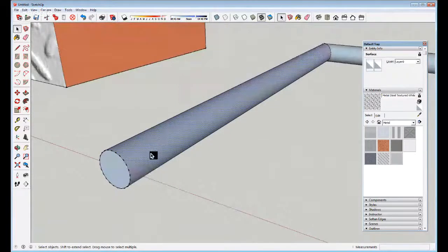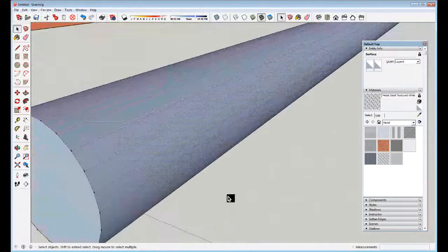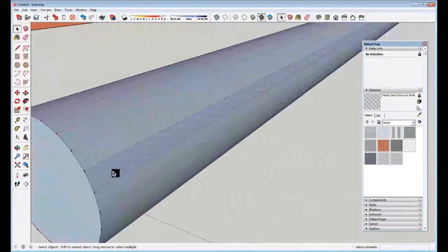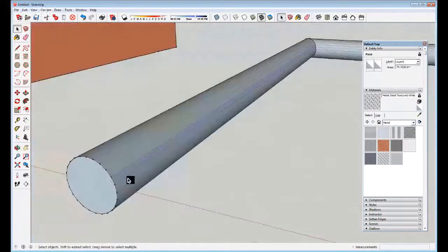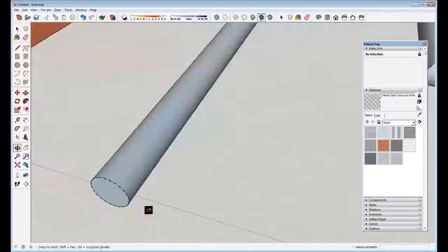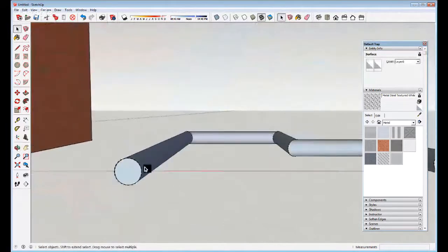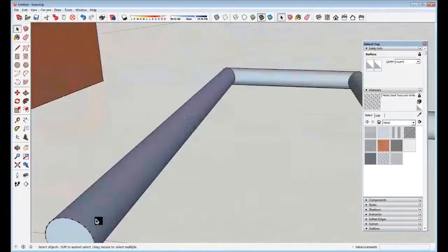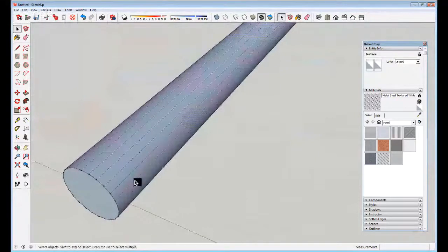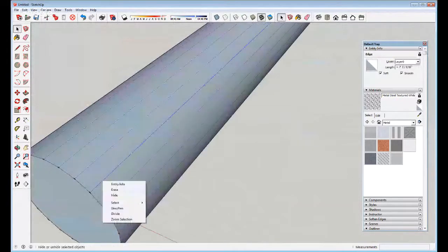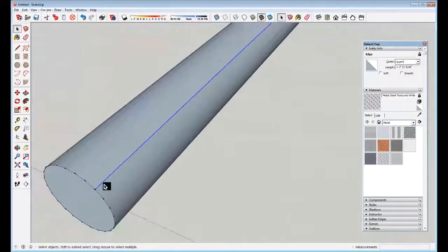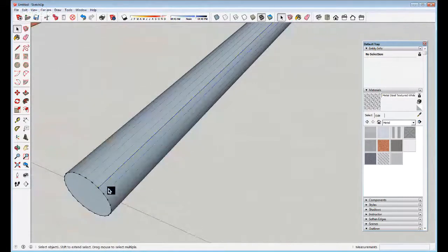I'm just going to quickly turn on the hidden lines here. This still has the lines, just so you know. It's just not showing them because you can visually trick things in SketchUp into looking like they're smooth, but they always have these planes. I can actually unsoften this and basically bring it back from being hidden.